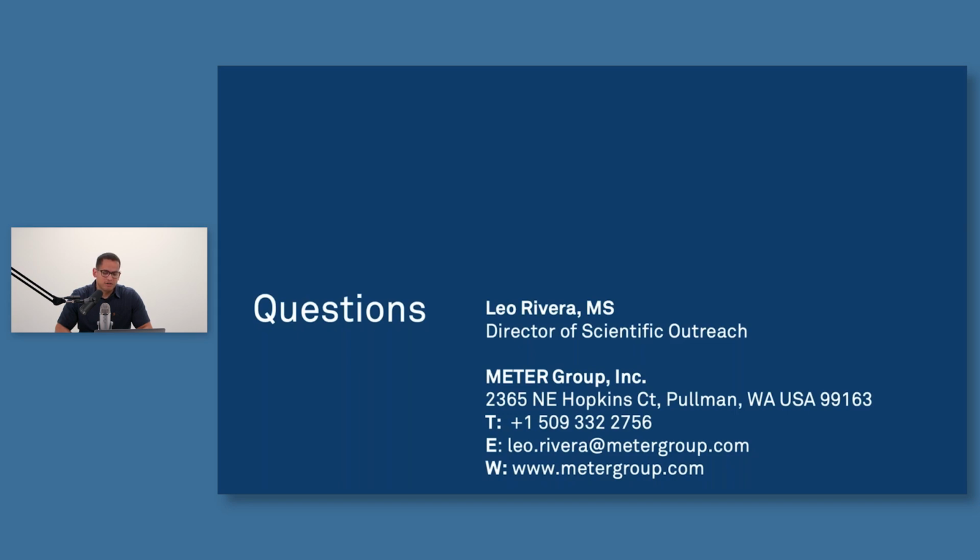I think what that tells us is that in some applications, you can get really good agreement between the lab generated data and the field generated data. For the example that I showed earlier with our site, we would see differences between the lab generated data and the field data. When you measure these soils in the lab, we see as much as a 48 to 50% saturated water content. We almost never see that in the field. So there are differences just due to trapped air, and also probably due to spatial variability, that are causing some of those differences between the field and the lab generated data.